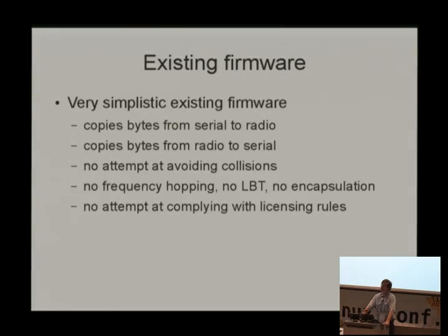And that really is no good for the sort of applications we have. First of all, it immediately violates a whole bunch of regulatory rules. You have to jump between lots of different frequencies if you're using, for example, the 915 megahertz band in Australia or the US. You have to have 50 different channels hopping between, with a maximum dwell time of 0.4 second in the US, 20 channels in Australia, and there's different rules all over the world as to how long you're allowed to sit on a frequency in order to be able to share the band with other users.